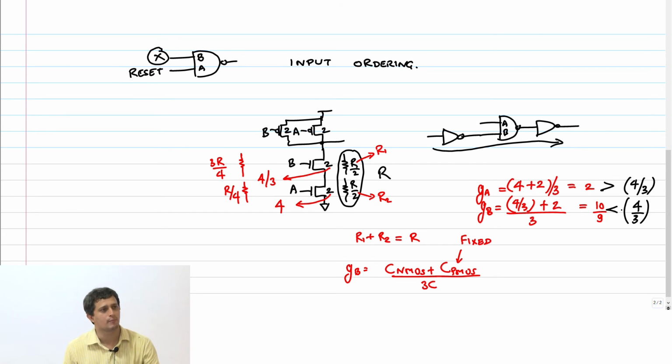So the same example that you take where you have a reset connecting to this, I will not only ensure that the reset is connected to the bottom transistor and the signal is connected to the top transistor, I will make the gate asymmetric, not skew it. I will make the gate asymmetric by sizing it like this. Of course, you can now do various kinds of sizing. This 4 by 3 and 4 is just one example. You can do any n plus 1 by n and n, or n plus 1, and get the same result, right? And in the limit, the logical effort of this critical input will approach what?